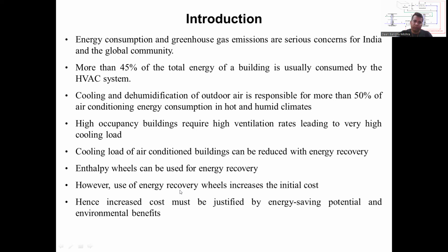When air is passed through the desiccant wheel, it is dehumidified and heated. But the application of these energy recovery wheels, like desiccant and enthalpy wheels, will increase the cost and also make the system bulky. And also their increase of cost must be justified in terms of their energy saving potential.